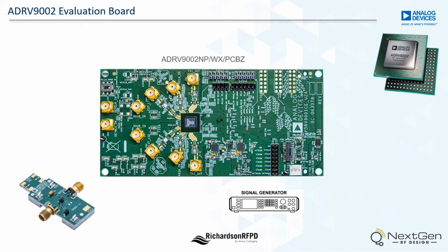This demo uses the internal synthesizers and an external signal generator as the reference clock to generate the LO source. The HMC8410 LNA demo board is used to optimize gain and noise figure.